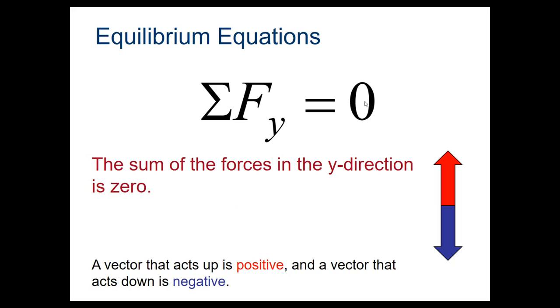Then our third equation is the sum of the forces in the y direction. So our vertical forces, same reasoning, have to be zero. Otherwise, our bridge would be accelerating. If the sum of our forces does not equal zero, that means it is moving and picking up speed, in this case vertically, and that again is not something we want our bridge to be doing. So, for our bridge to be sitting still, all of these things have to be true.